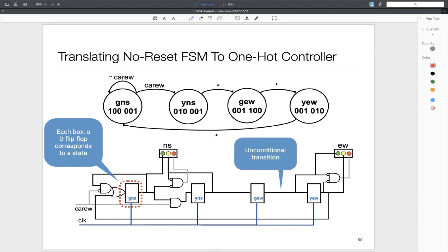And then the question becomes which binary coding. Which one do I call 00? Like in this case, let's say I was using 2-bit coding. Which one should be state 00? Which one should be state 01, 10, 11? That can have an impact too. So the tools which do design actually have algorithms to figure out what is a good state mapping also. There's a lot of research on that topic, and people have developed algorithms for doing it. I'm talking about research from the 1990s or so.